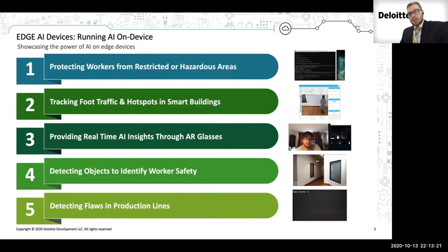What we'll be showing here is several selected use cases of where we're running AI on these handheld edge devices, such as the Raspberry Pi, the Intel NUC, the Nvidia Jetson line of products, and utilizing these USB accelerators that you can plug into existing hardware to make it more AI powerful and be able to achieve that 15 millisecond inference speed on the device.